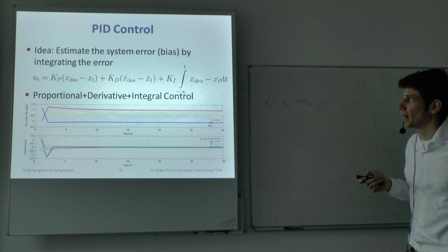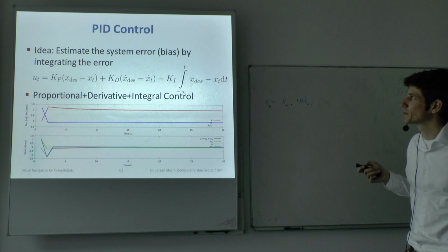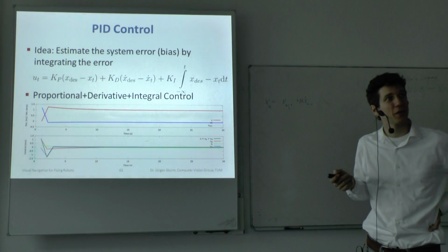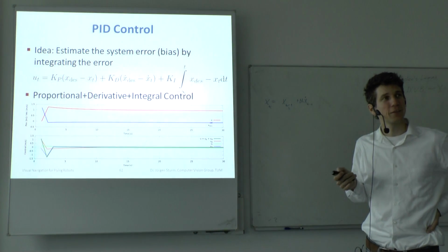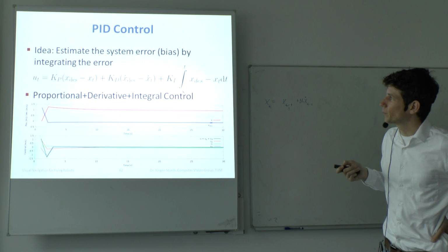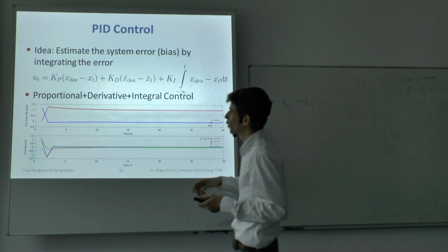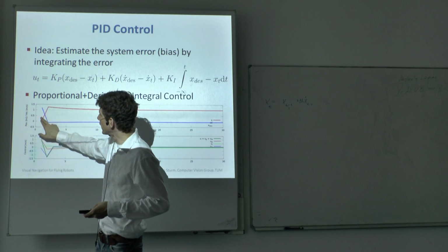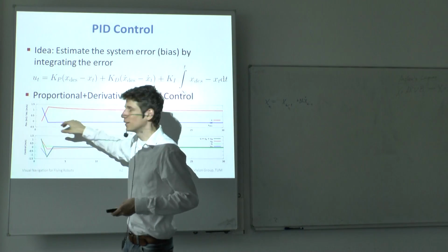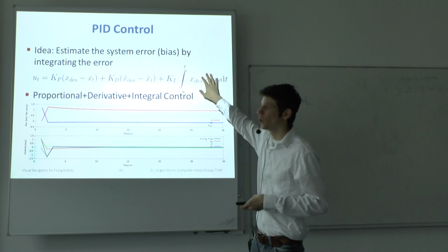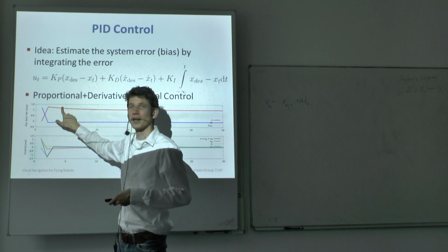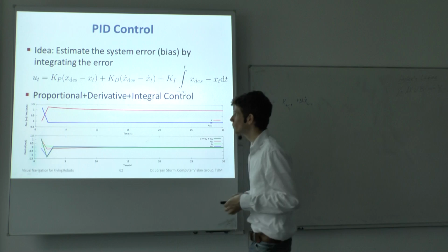This leads to a small bias here, but hopefully at the end the whole thing will converge on the right desired value. If you look at this curve, you're right, it's the distance. This area and this area have to compensate. So this part won't give 0 control output as long as this area and this area are not the same. True.